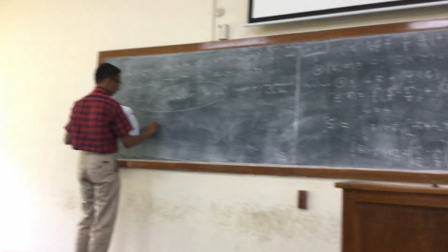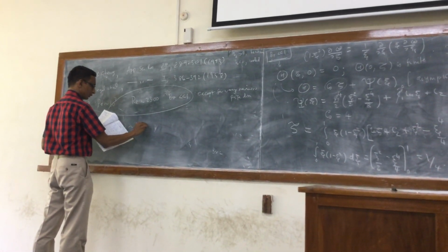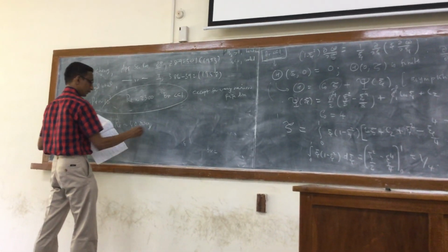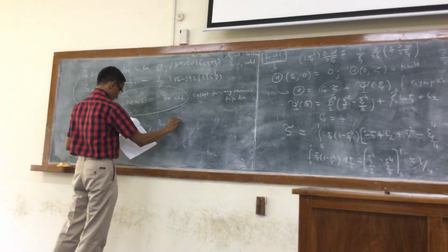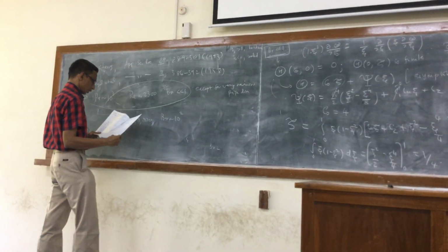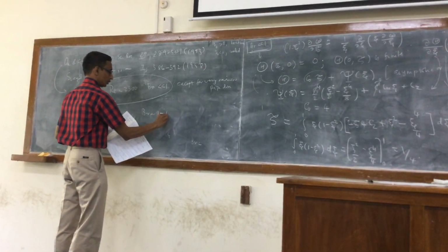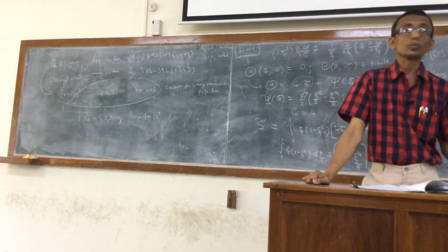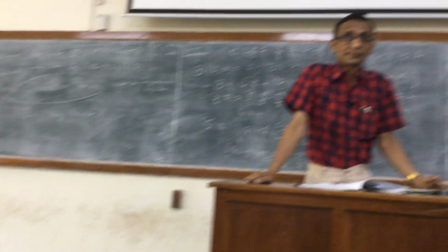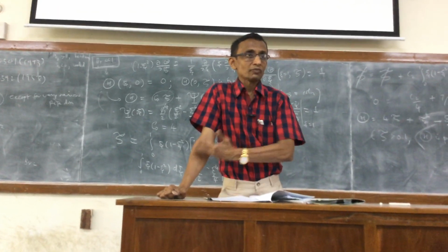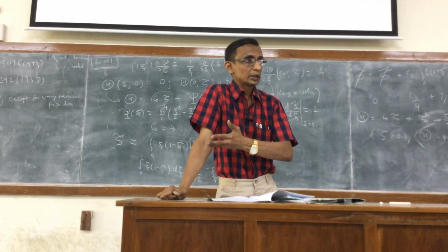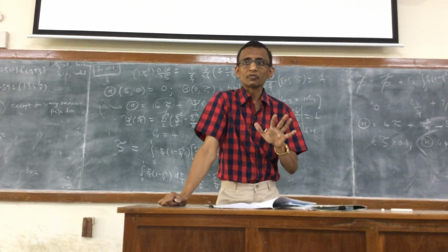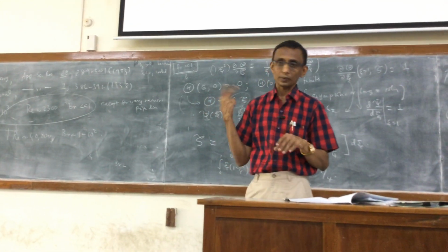applicable. So for Reynolds number very high, the turbulent region, for this class of fluids, they say the Brinkman number would be of the order of 100, and of course this varies depending on the pipe diameter, and so you would have to take into account the viscous effects, right? Then one of these papers also provides how to get the solution when the viscous dissipation term has to be taken into account. So all kinds of generalizations are available in these papers, so you can take a look at that.